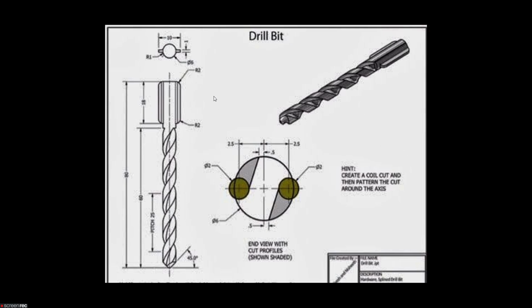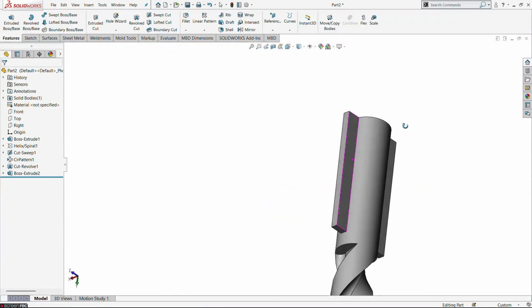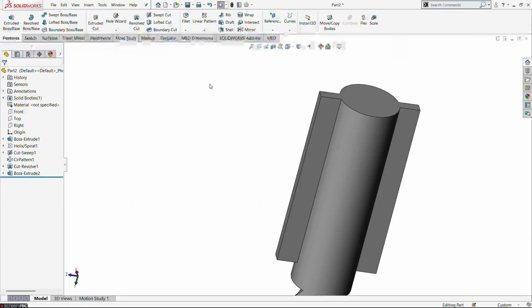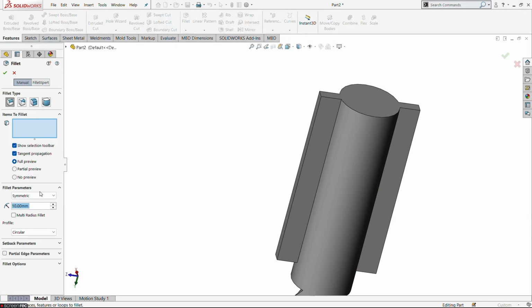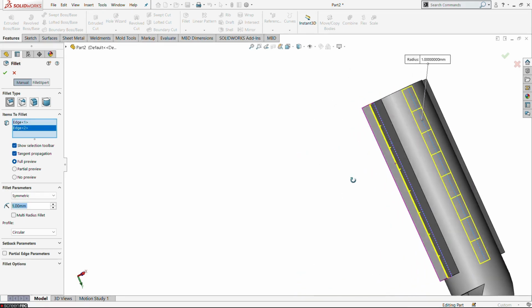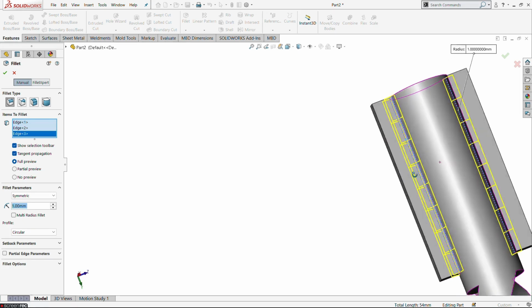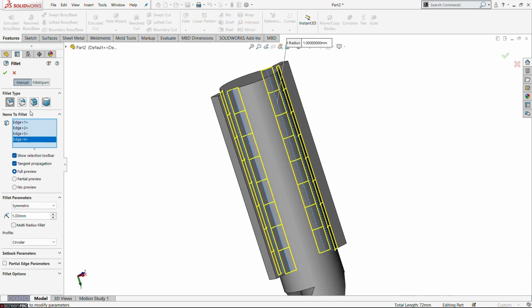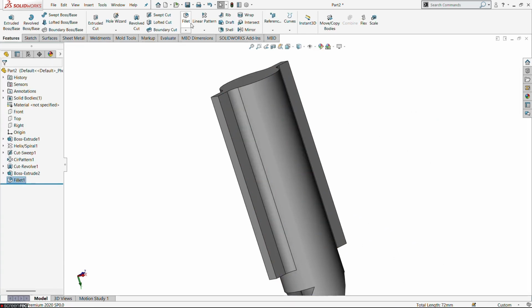Let's form a fillet to combine them with each other. Now choose the fillet option. What is the fillet for these first two portions? That vertical line area is 1 mm radius. So mention 1 mm radius and choose all vertical lines. Fillet them one by one. First one, second one, third one, and fourth one. Once we create these fillet formations, then exit the sketch.